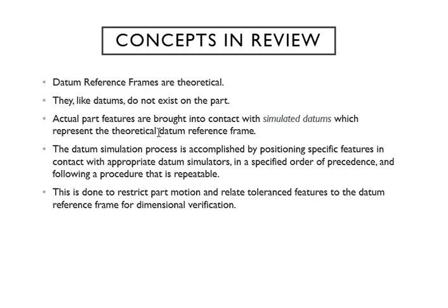Review. The datum reference frame, again, is theoretical, not physical, and doesn't exist. Since it is theoretical and not physical, your actual part features have to be brought in contact with your simulated datum in order for us to realize the datum reference frame. So your theoretical datum reference frame is going to represent your part feature.